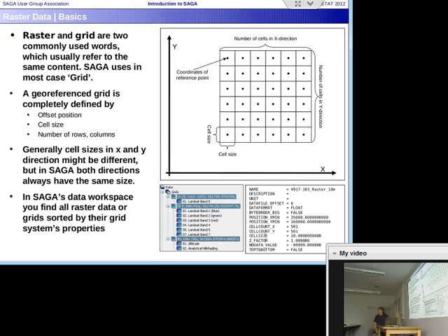It's a bit sensitive, the grid system. If you have basically the same grid system, but it's been rounded with different decimal places, it's not going to recognize it as the same grid system. It's sometimes a problem. Yeah, I know these things from R. But I think it's a bug. It's mostly if you have lat-long coordinates with very many digits, but also with metric coordinates. Even if I have a few more digits or something, the numbers are exactly the same, and SAGA doesn't recognize it as the same grid system.